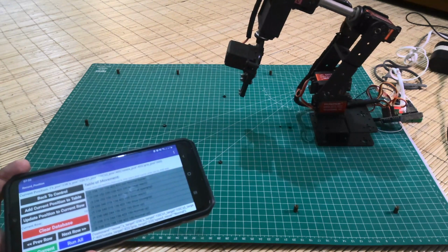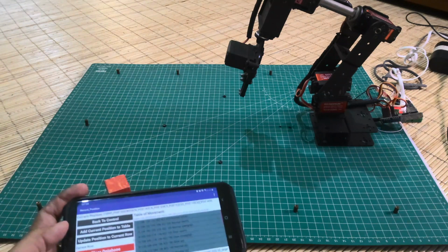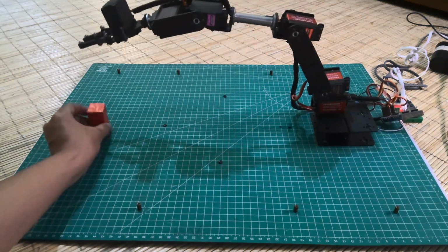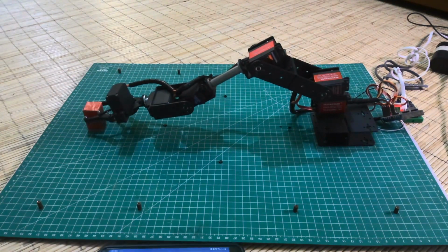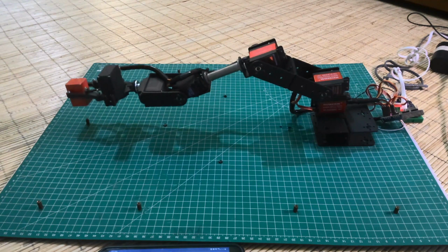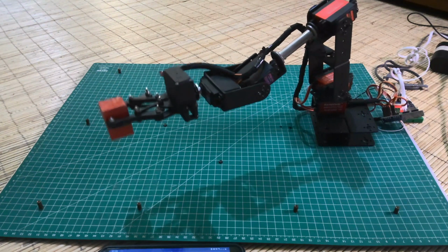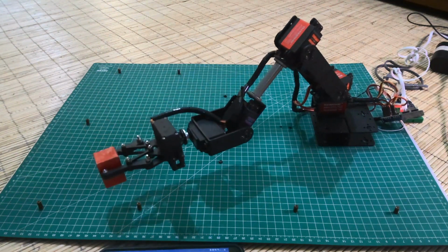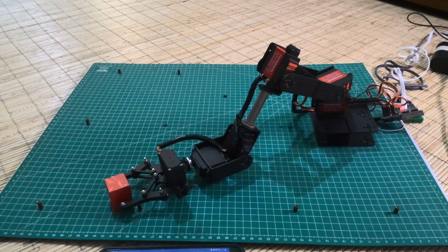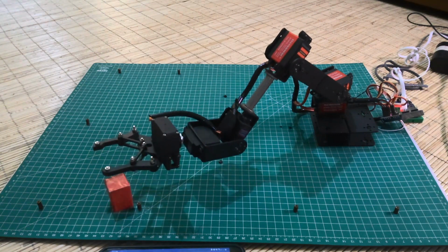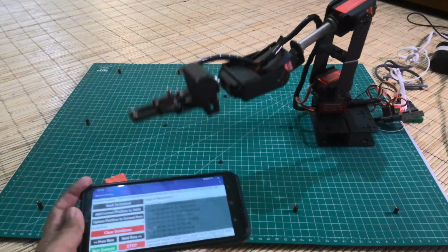In this video, we've successfully demonstrated the wireless control of a 6DOF robot from an Android smartphone using MQTT communication. The showcased features include the ability to record robot movements into an SQLite database via the Kodular app. Users can easily control the robot manually and smoothly execute recorded movements through the provided interface. With the Run All button, users can run all movements sequentially, and the Stop button allows them to halt the movement whenever needed. Overall, this video illustrates how the integration between hardware, ESP, and software, Android app, can provide intuitive and flexible control over the robot.